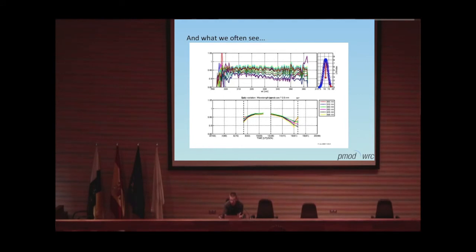So from that information, you, as an operator, would have to go back to your instrument and investigate where that problem comes from. This type of comparison will never be able to calibrate your instrument, because how should I produce a calibration from variable data like that? You could have a calibration at noon or in the afternoon. You actually should try to find out why your instrument is behaving that way, resolve it, and then you will have a better instrument.